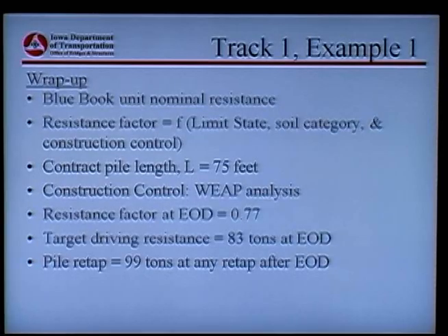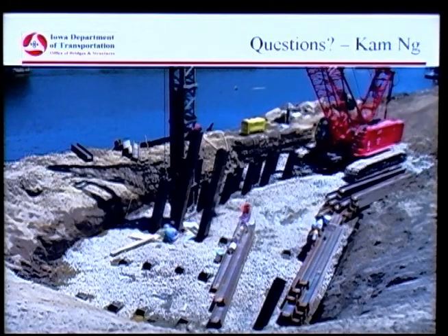Target driving resistance, this is at end of drive, of 83 tons. With retap, 99 tons. The 99 gets us to where we need to be in order to satisfy the structural engineer's need for demand. And that brings us to the end.